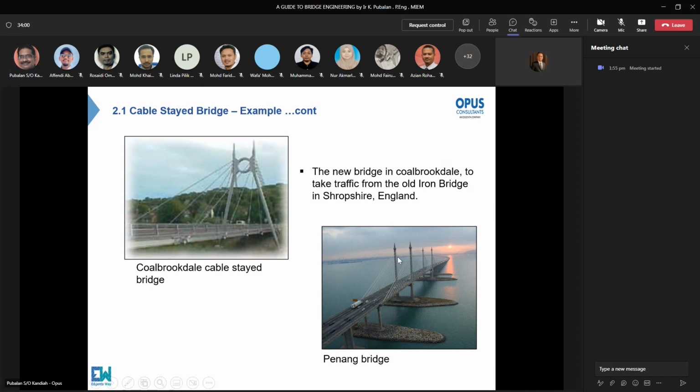As you can see, on Penang Bridge, the cables are at a height, and the height of this pylon is easily about 60 meters on top. So these cables are flexible in the sense that inside the ducts, you have the tendon and there is no concrete or grout filling inside. So actually, when you have high wind and rain combined together, the cable can also vibrate.